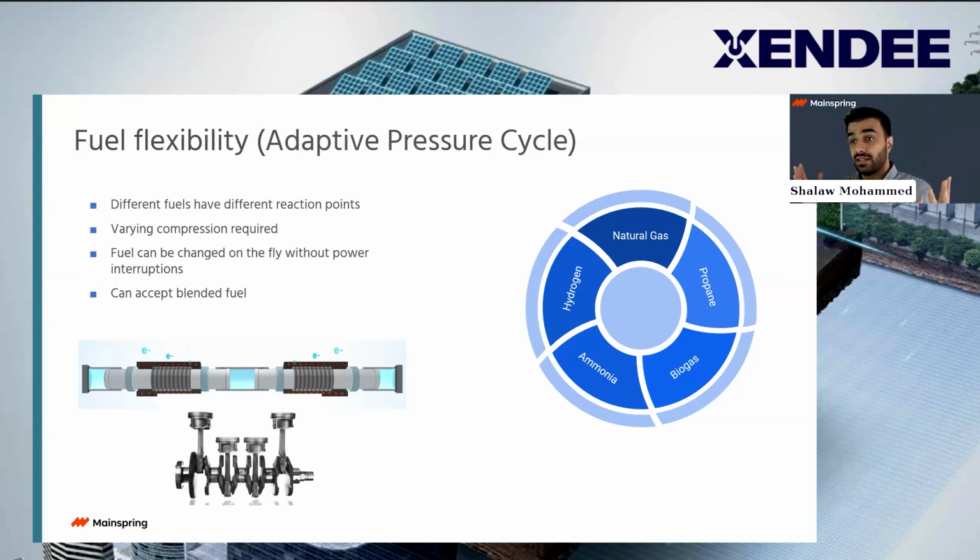But in the grand scheme of things, that's nothing, because from an electrical output point of view, which is what we care about because we're generating power, there's zero disturbance, because we have a DC bus. So we're rectifying, and we have pure power quality going out of that inverter. And we can do any of these fuels that you have on the screen, as long as it's a gaseous fuel, you can go ahead and put it in the system. The system would automatically figure it out and adapt to it. And you can do a blend of them. You don't necessarily need to just change the fuel. We only have one point of connection when it comes to the fuel. The blending, or the change, has to be done outside, but you don't need to notify the system. You can just go about business and change the fuel on the fly.